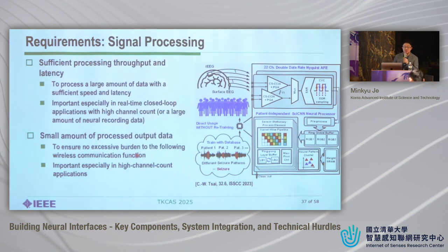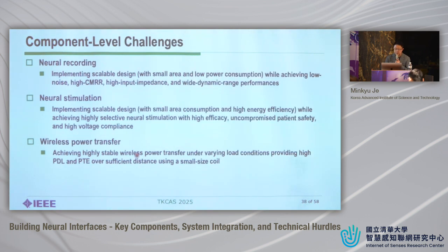So when we increase the number of electrodes for scalable brain-machine interface, even if we improve our wireless transmitter technology further and further, eventually we will face the limit, okay? So to overcome that limit, we have to combine our wideband data transmitter together with this on-device signal processing function so that we can reduce the amount of data we have to transmit, okay?